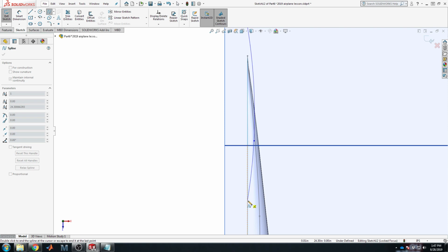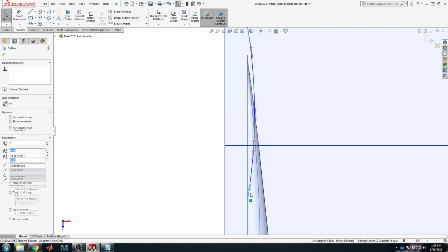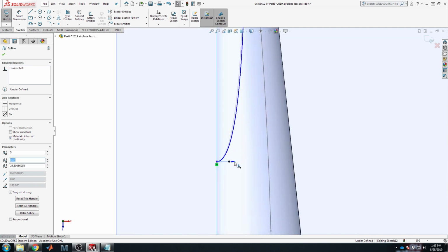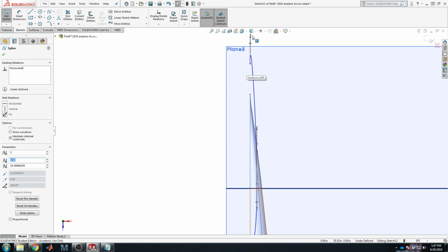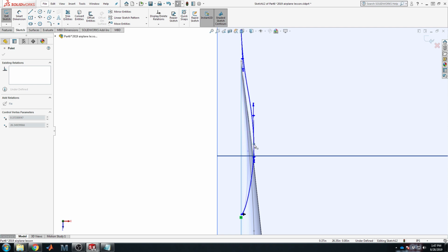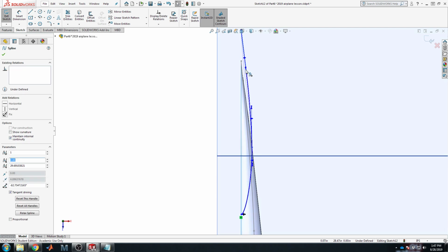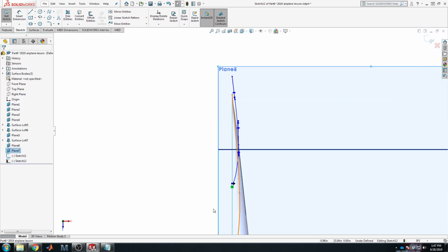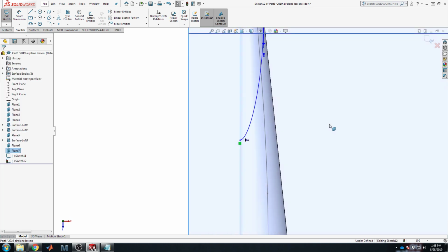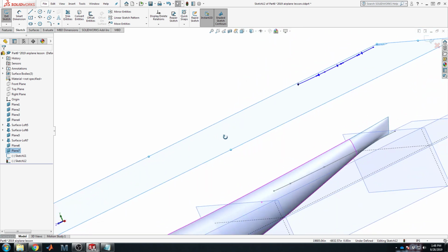Okay. Let's just go to the leading edge, and fewer control points this time because the shape's very, very simple. I do want to have that horizontal, so the leading edge creates a nice stagnation point there at the very front. Turn this around because that would make no sense to have an inverted trailing edge. And honestly, I want to preserve similar structural thickness, so we have a very stiff vertical tail for the entire thing. Okay, so that should be fine, maybe a bit shorter. Just look at it proportionally, see if that makes sense.